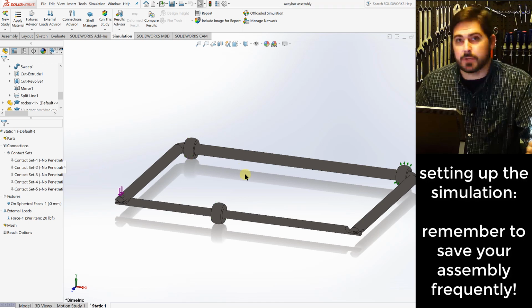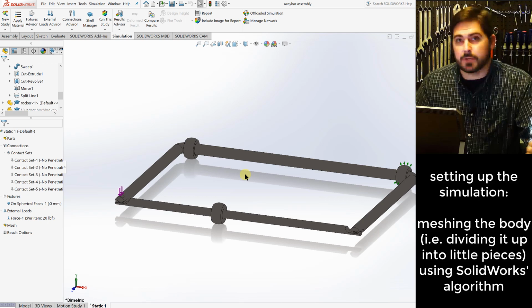And what I want to do now is to do these simulations. What it does is it takes the material and it splits it up into small pieces, small enough pieces so that each piece has a pretty simple way that it actually will deform and change and, you know, have stresses in it. And then you take a bunch of those pieces, usually they're tetrahedrons, and you stack them all up together to basically approximate the geometry of what we are really trying to analyze. And that process is called meshing. You basically are making this, you know, spatial mesh out of the part that we're looking at. So I'm going to do that here.